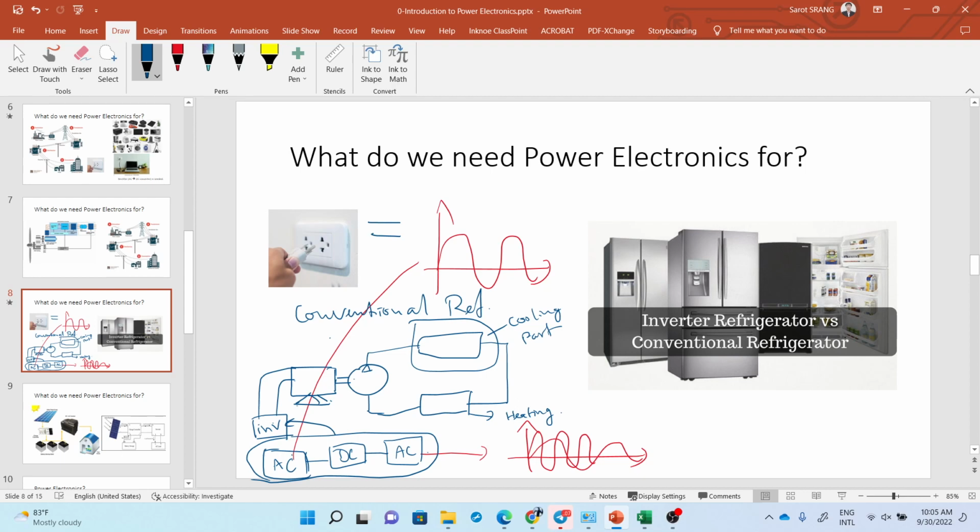In this case, you want to control that in software, you need it to turn the temperature up or down. There are two levels of control: one is on the inverter side, and the other is on the cooling room. Your question is about the cooling room, where you need a temperature sensor to give feedback to the motor control. The set point is sent to the microcontroller for controlling the motor, and the motor here includes the driver. The inverter is a kind of driver.